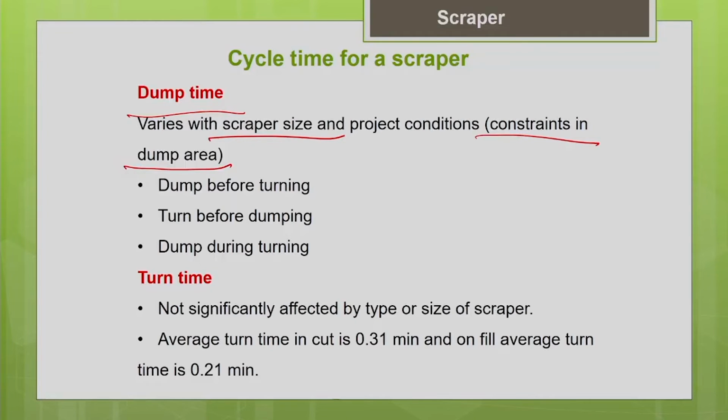That is why very commonly you can see that if the terrain is very hard, with very tough consolidated clay, then in order to enhance the productivity of the scraper, they initially use a bulldozer with a ripper and rip the soil. They loosen the earth so that you can easily use a scraper for the loading operation. That way you help the scraper to reduce the loading time.